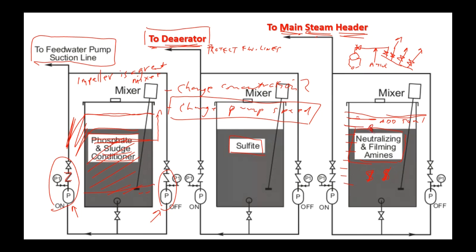And this one here says add 100 milliliters of amine. So when you go into a tank, where they have day tanks, they'll usually have marks on the tank, and the marks are going to be evenly spaced, and one is going to have some little comment about how much of the chemical to add, and the whole idea is to maintain a constant concentration.